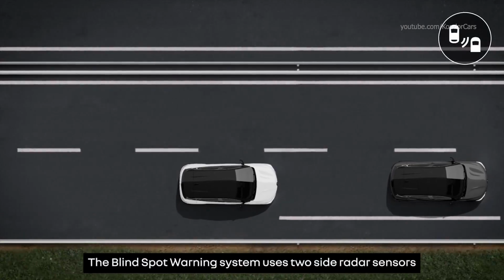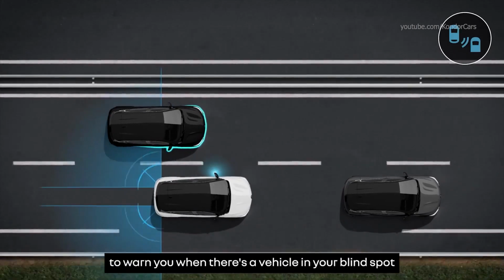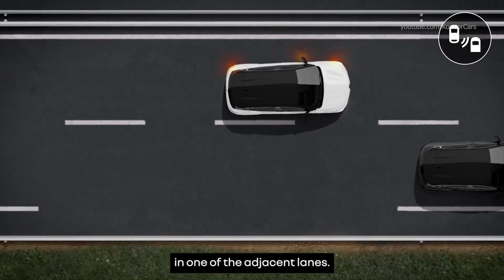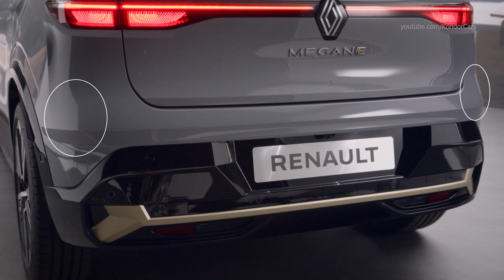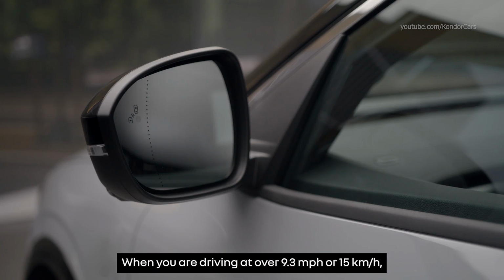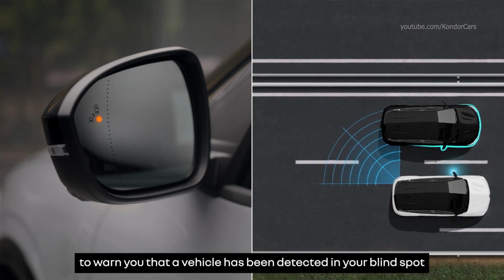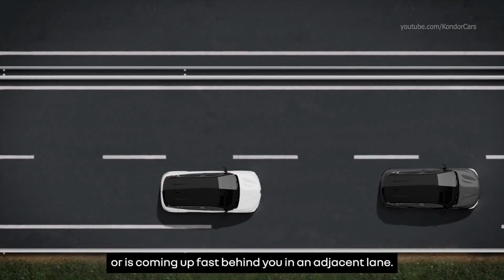The blind spot warning system uses 2 side radar sensors fitted on both sides of the rear bumper to warn you when there's a vehicle in your blind spot or when there is a risk of collision with a vehicle traveling faster than you in one of the adjacent lanes. When you're driving at over 9.3 miles per hour or 15 kilometers per hour, this orange indicator lights up on the left or right-hand wing mirror to warn you that a vehicle has been detected in your blind spot or is coming up fast behind you in an adjacent lane.